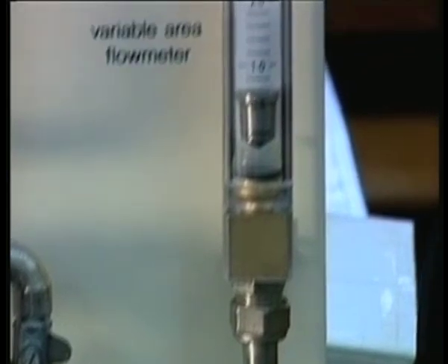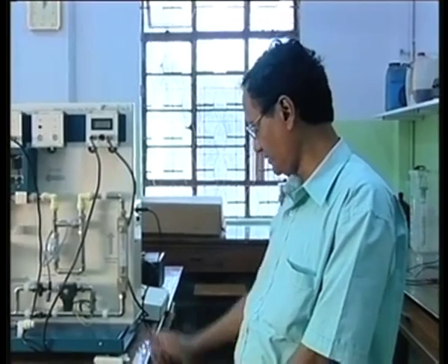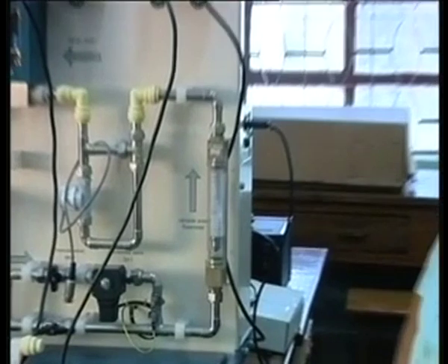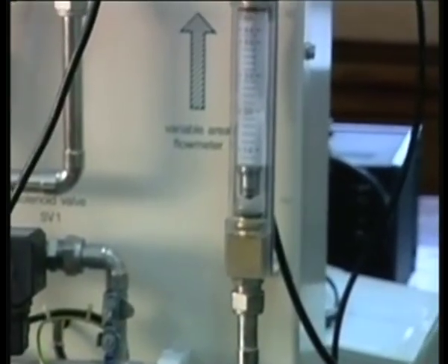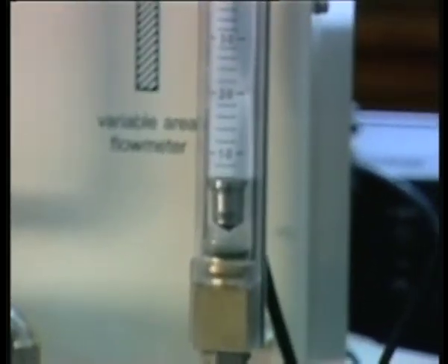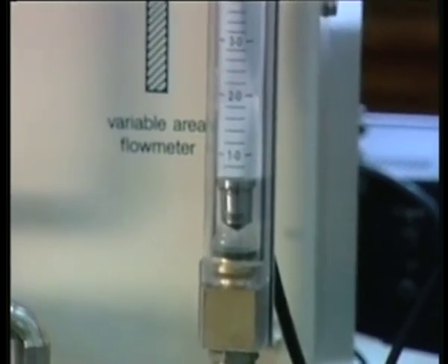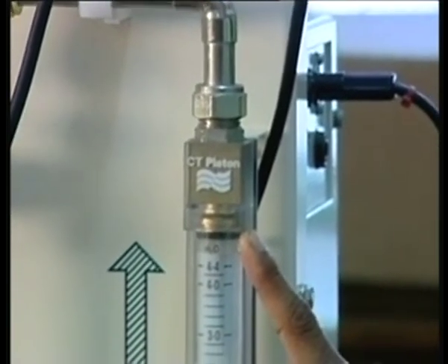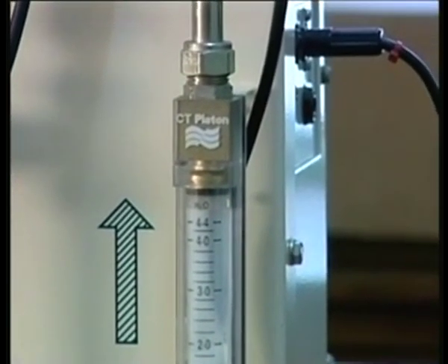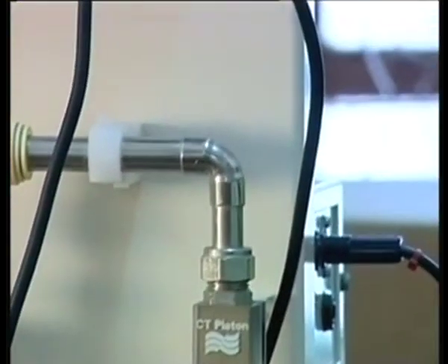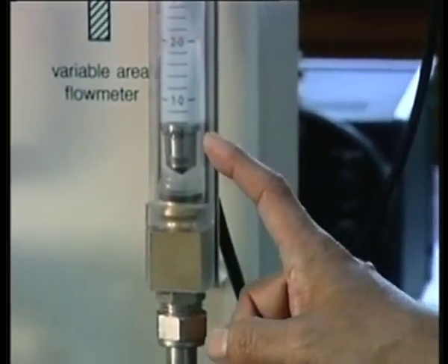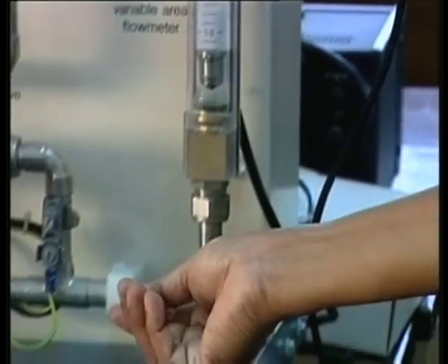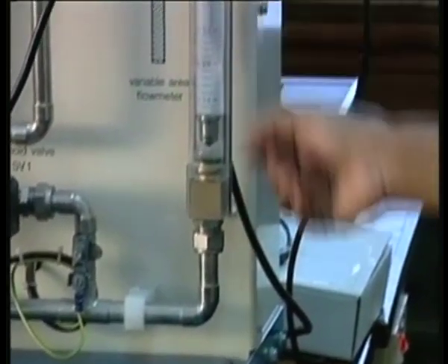Now I will describe at least two sensors. One of these is a rotameter, which is a flow meter. It gives an estimate of the flow of the liquid in the entire process. In the rotameter there is a taper tube with a very small angle, and the liquid comes in from this side and goes out through that side. There is a float, which some technical persons also call a bob. As the liquid flow increases, this bob will move up.